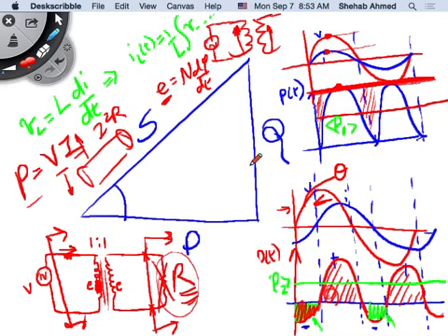It's seeing that 100 kilowatts pass through, because that's what happens here, right? The load current will eventually pass through from the supply as well. But it's also seeing the reactive power used to set up the magnetic fields. So I have to rate it to something that is a combination of the active power that's consumed, the real power consumed by the load, as well as the power that's consumed to create these magnetic fields. Right? The real power that's consumed is called average power.